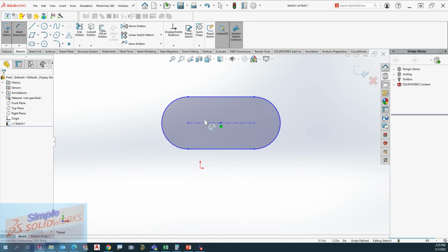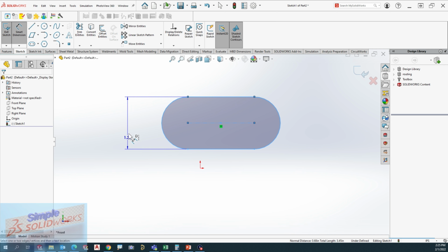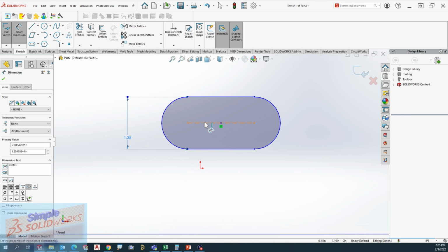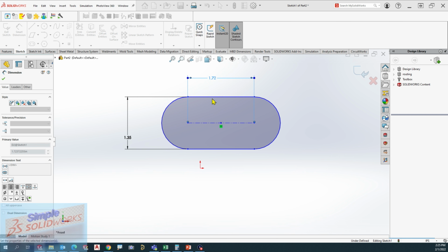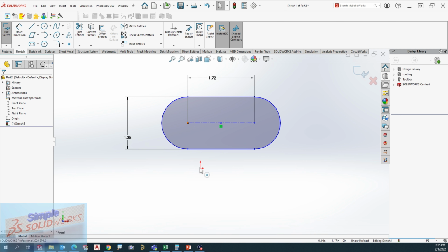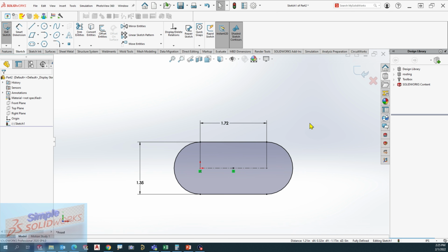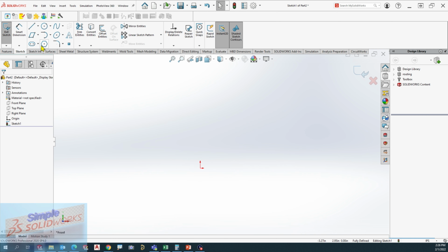And again, you can always pick the circle of it and say, I want this to be that, and say okay, that's fine there. But then I want to pick the center of this, and that's fine there. If you take it from here to there, and you hold your shift down and select, it turns black. So now it's completely constrained, and it has this parameter there. So I think this is a good one. I've used this slot command the most.